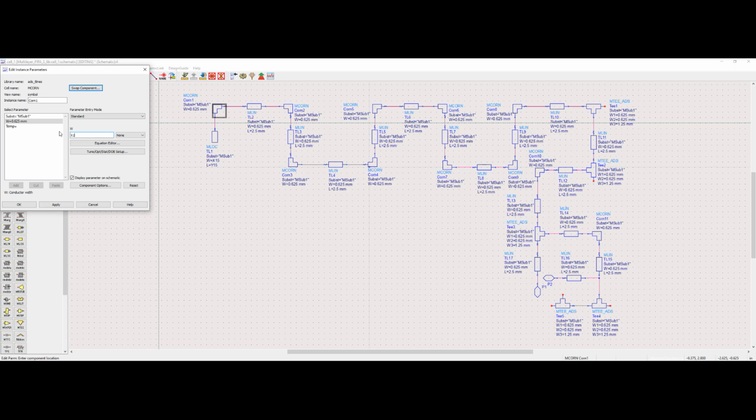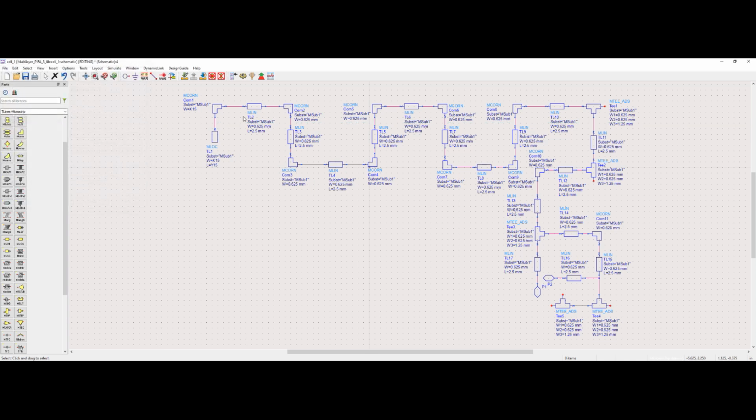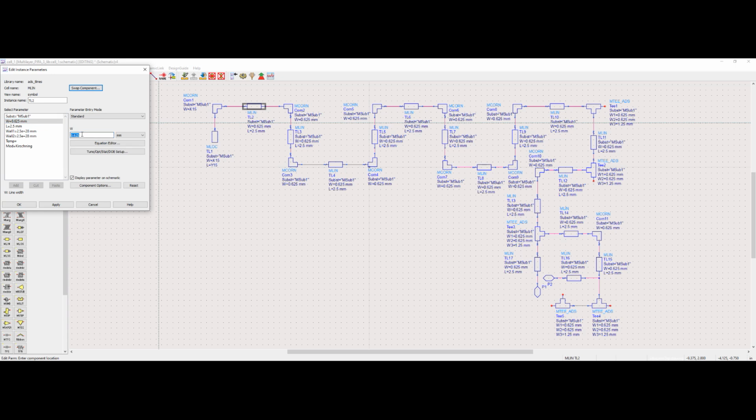If you can recall, previously we defined the default value with unit mil. Due to this, the microstrip schematic components should not have the unit on them. Otherwise, they will have double units, which will result in wrong width and length parameterization. Due to this, the correct way to insert the width and length parameters into the microstrip schematic component is by double-clicking the component and inserting it. While inserting the parameters, the unit will disappear. Since our intention is to get rid of the unit, we can ignore this.